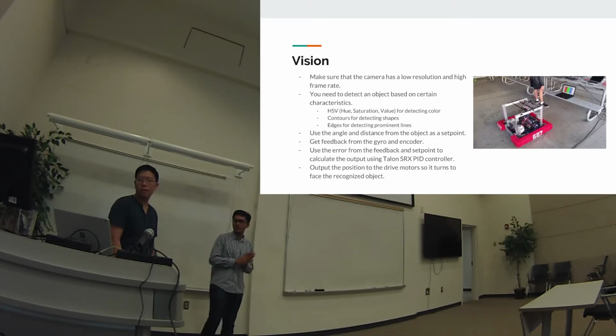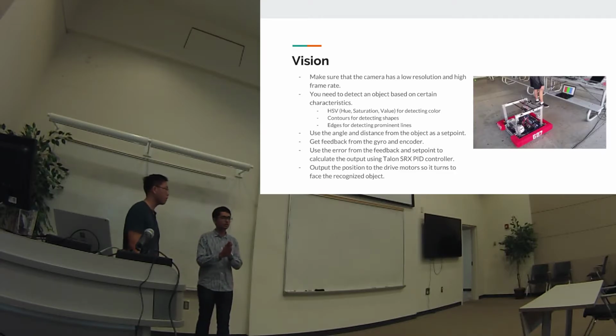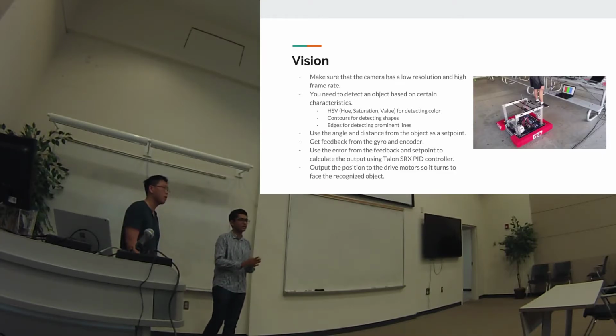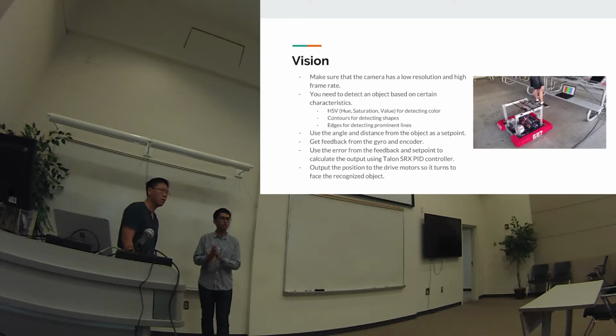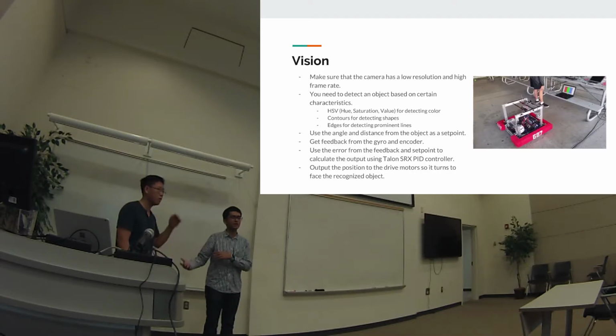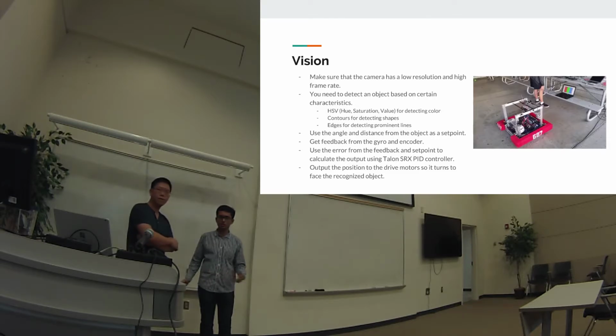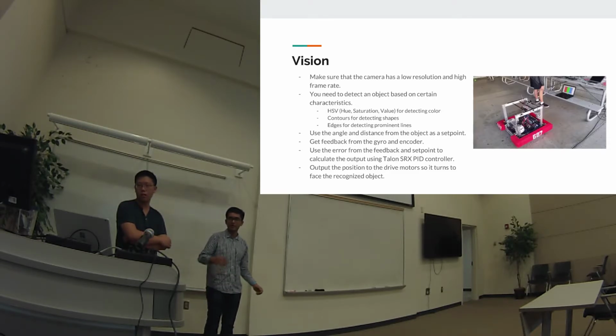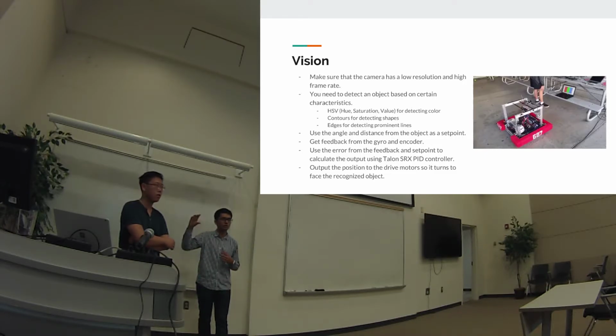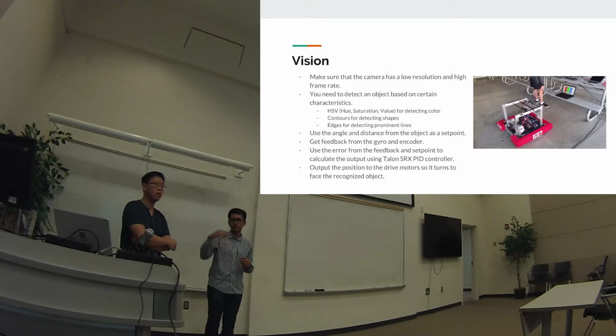The great part about using vision is, like Justin said before, you don't use it as an input for your control loop. You use it to guide the NavX and the encoders of where to go. In this example, you can see that it uses turning for vision. This was a really great example in the 2017 game, where the reflective tape was there when you're shooting fuel.